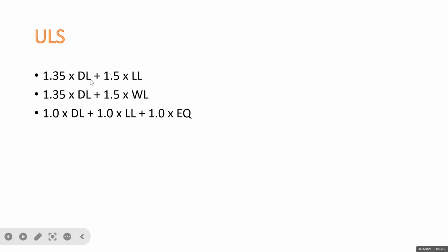Dead load, as I explained before, is the weight of the material. It can change, but the live load is the load that can move. It's like our steps on the floor. The car on the roads generates a live load on the roads, because the load can change and vary.